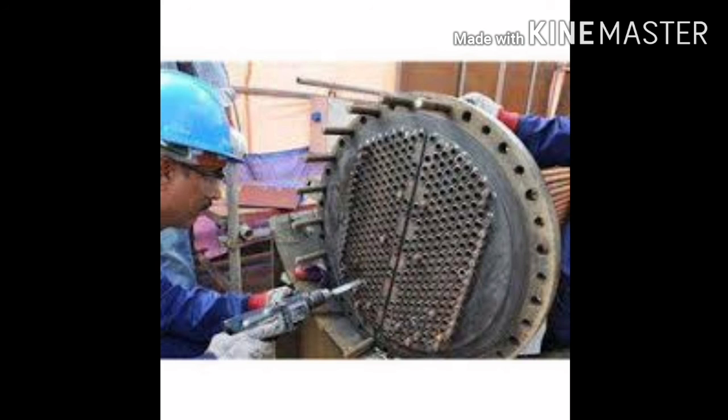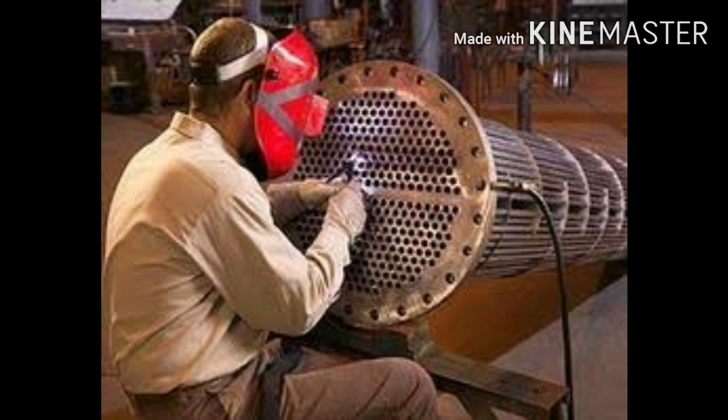Okay. Number 2, release the pressure from the heat exchanger. Ensure that the pressure gauge indicates 0 bar. Number 3, drain out hazardous chemicals from the heat exchanger. 4, be careful when selecting chemical cleaning material for the tube. Improper selection will cause corrosion. Number 5, if chemical methods are used for cleaning the tube side, take care not to cause tube defects. Mechanical cleaning can cause injury to people too.